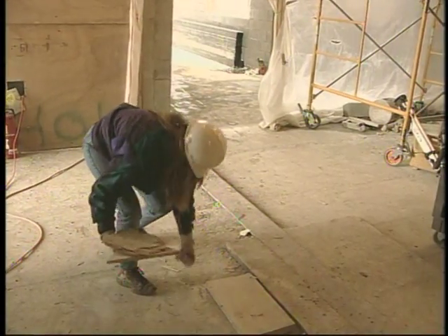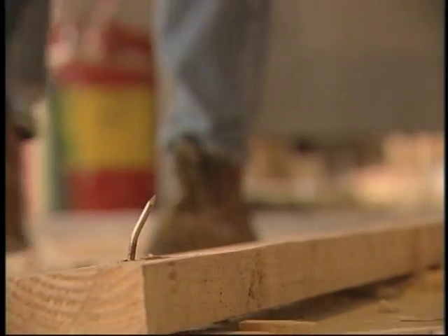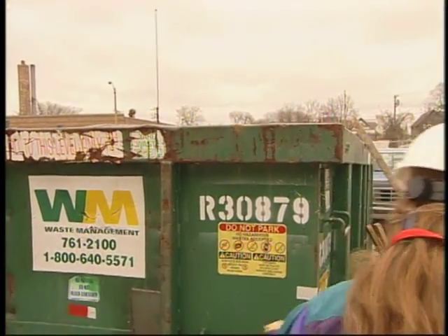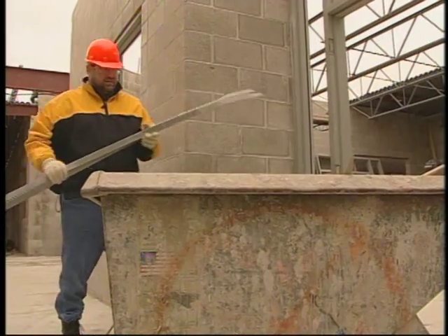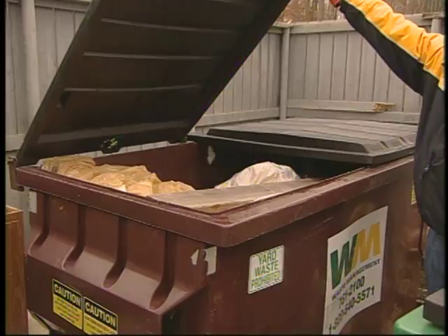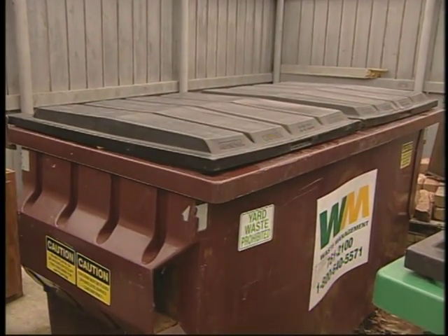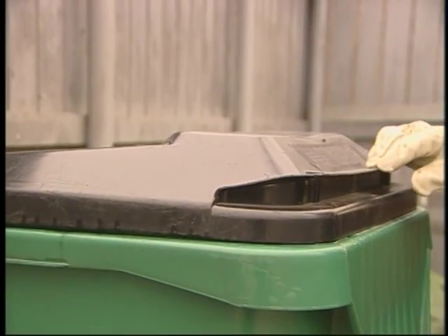Pick up any object or piece of debris that someone could trip on, even if you're not the one who left it there. Be on the lookout for form and scrap lumber with protruding nails, and make sure to dispose of it properly so no one gets hurt. Glass and other sharp objects, such as sheet metal, must also be properly disposed of. Use trash containers with lids for the collection and separation of all waste materials. Make sure to replace lids after you've disposed of debris. Lids should have a firm fit.